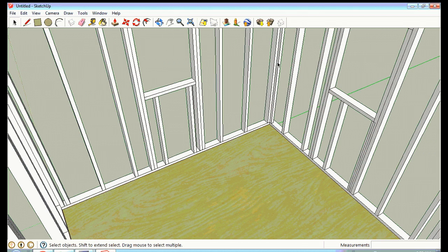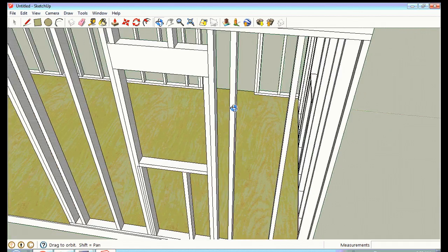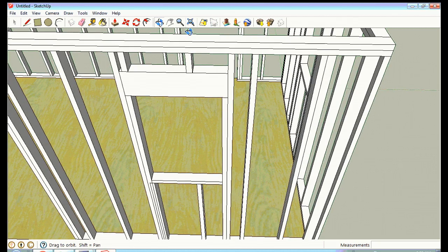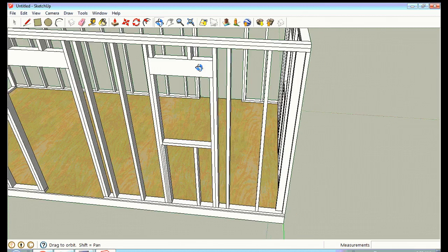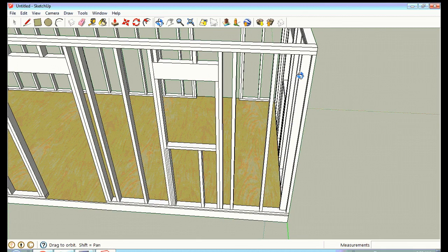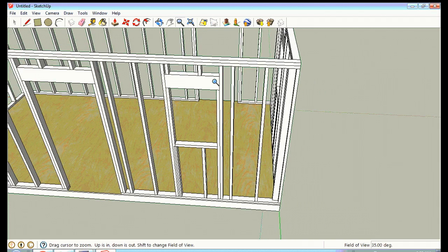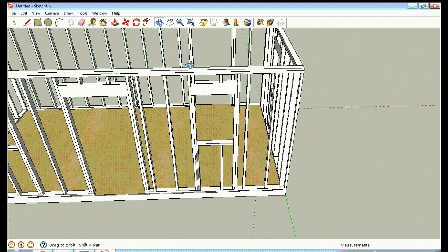I've got a nice surface face to screw this entire 2x4 to over here, and I'm still using two 2x4 studs for a corner brace, but because I changed the direction on it, I've got a better pocket there for putting in insulation. So that's called a California King corner, and is how I build my structures. Works a little bit nicer, and gives you a better place to put your insulation in. Now I would do that to all 4 corners, but just to save time, we're not going to do it. I won't show it in all 4 corners. I just wanted to show you how I construct the corners.